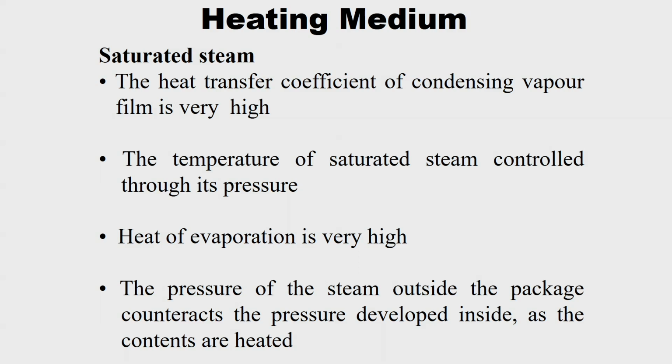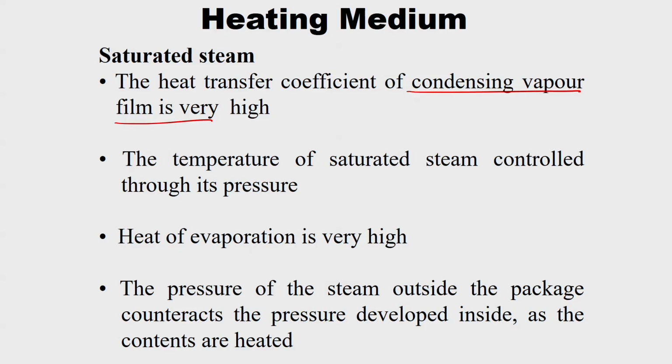What are all the heating media used? The most famous is saturated steam, because of the following reasons. One is that the heat transfer coefficient of the condensing vapor film is high. When the heating medium is given into the retort, after some time the condensing vapor forms a film near the packaging. If the heat transfer coefficient of that film is low, then that will add an extra resistance for the heat transfer. So this is very high, so we will not have any issue. That is one reason.